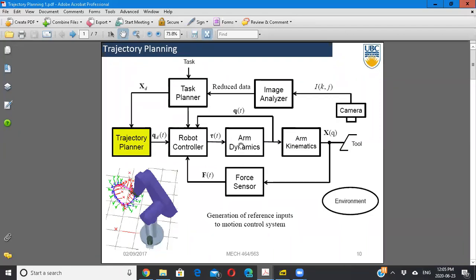And then before even that, if you were to simulate this robot, you can come up with some equations which can tell you that if you input this much torque to each joint, the unit of torque is Newton meters. So let's say you give 1 Newton meter to joint 1, 2 Newton meters to joint 2, 3 Newton meters to this, and so on. Then what will be the acceleration of each joint? And from that acceleration, you can double integrate it to find the joint positions.